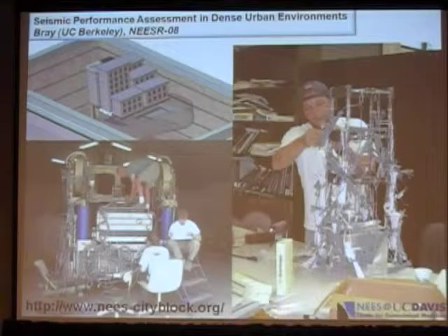The other thing to think about with a model like this is every one of those strain gauges is probably a $400 application by the time you figure in the installation and the connectors and the wires and the labor of actually installing that thing. And so if you have that structure with 70 or 80 strain gauges on it, you're in a $35,000, $40,000 structure. They're not cheap little things that you run down and just test because you think you want to do a test.